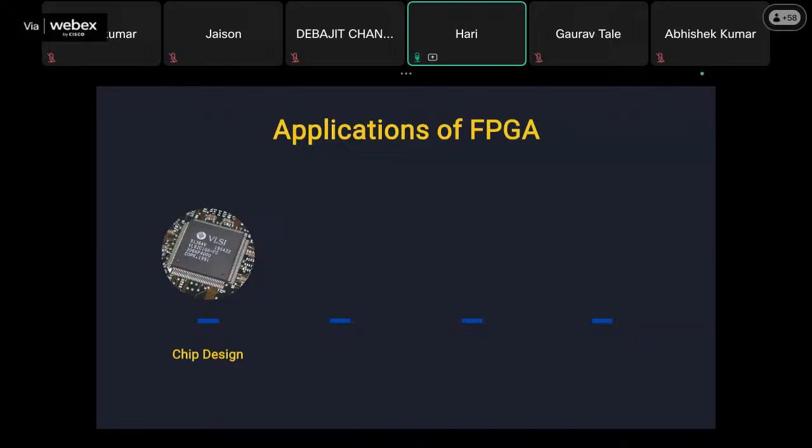I'm speaking very little about verification, but industries use FPGAs to do a lot of verification. They don't want to spend billions directly deploying an ASIC. Instead, they will use expensive FPGAs to virtualize all the functionalities of their ASIC first. Only then will they start designing the chip itself. So that application comes into play.